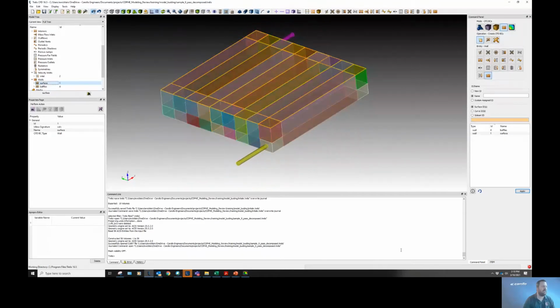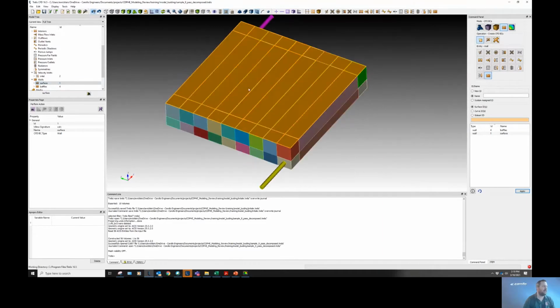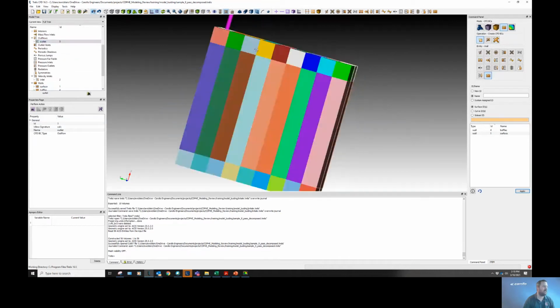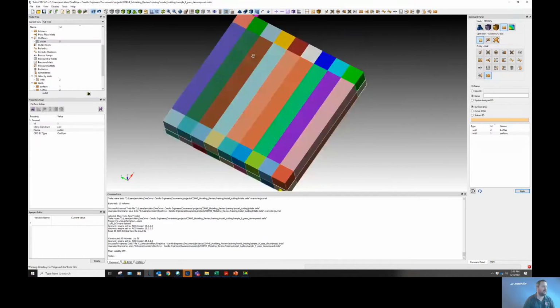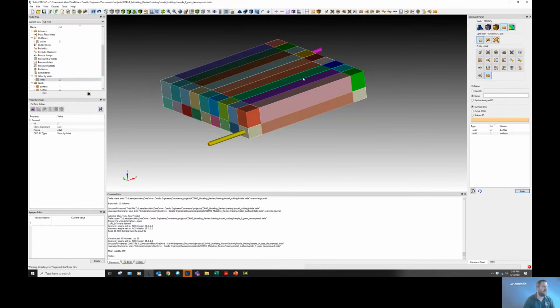We're going to be using a rigid lid approximation as mentioned in the last module. So we've assigned the surface as a wall boundary called surface. We've got an outlet boundary assigned at the outlet pipe here. So the flow will enter from the inlet, travel through the domain and exit there.